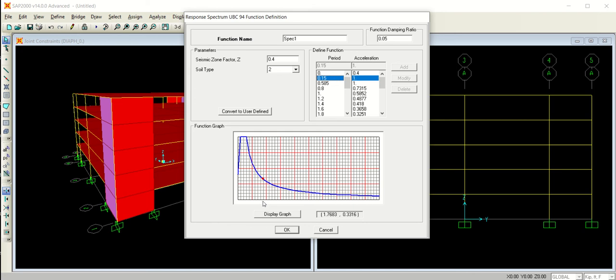For example, you are going to the tall structures of time period 2 seconds, which is almost equal to a 20-story structure. So the demand is now reducing. Okay, the g value is reducing to 0.3 g. And when you are going further, for example, a 100-story structure, the demand is reduced to 0.06 times of the g. So this is what response spectrum tells you about.